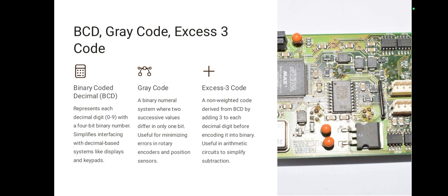Another type of code is the alphanumeric code, which digital systems require in many situations to handle data that may consist of numerals, letters and special symbols. Therefore, it's necessary to have a binary code for alphabets also. If we use an alphabet binary code, we can represent 2 to the power n elements with this code. We need a minimum of 6 bits, that is 2 to the power 6 equals 64, as we can see in the case of the American Standard Code for Information Interchange, that is, ASCII code.